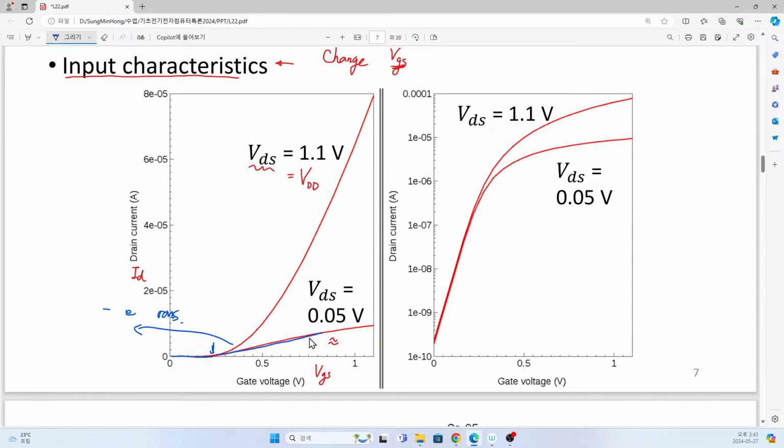Of course, in contrast to our real electron charge versus VGS relation, here we have a little degradation. This is not exactly linear, and its slope is continuously reducing. It is because this quantity is not only a function of Qi, the inversion charge density, but also a function of our effective mobility.